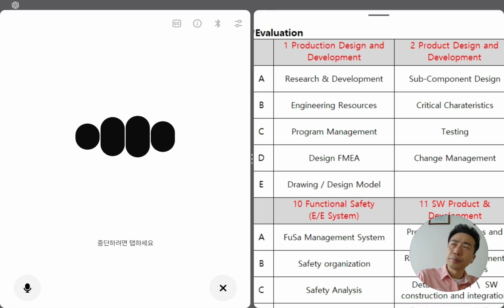6. Can you demonstrate how your system ensures traceability between design changes and production implementation? Answer: Yes. Every design change is linked to a change notice and a revision number. The system requires confirmation from production that the new version is implemented. We also record training and inspection results to prove that production is using the latest drawing.